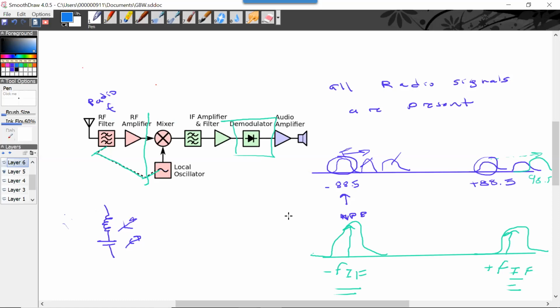An amplifier, and then another multiplier. Now, the old way of doing it is the multiplier, it's just a local oscillator that you tune just to the frequency in question. A superheterodyne is such that it's a local oscillator so that when you multiply it together, you get the same intermediate frequency no matter what.